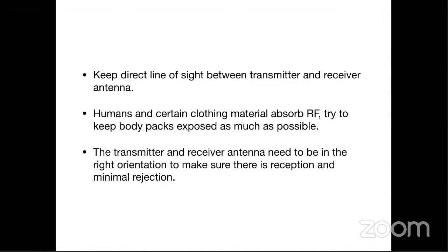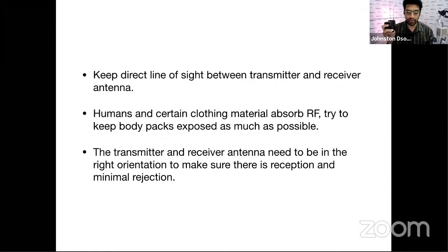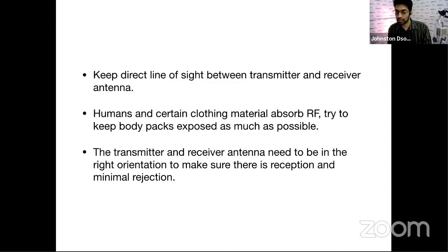Okay? And also with these things, right, these are very low wattage. The power is comparatively low in these. So they're not meant to be used over large distances, only short distances. And what is going to happen if you're working for broadcast, like for a news channel, and you're working with the camera guy, and you go to cover some event? There are probably 100 news channels, and all of them have these. If you don't take proper care in doing these little details, you might not have proper RF. Okay. In those cases, in crowded environments, it's very, very necessary for you to tune the systems properly.